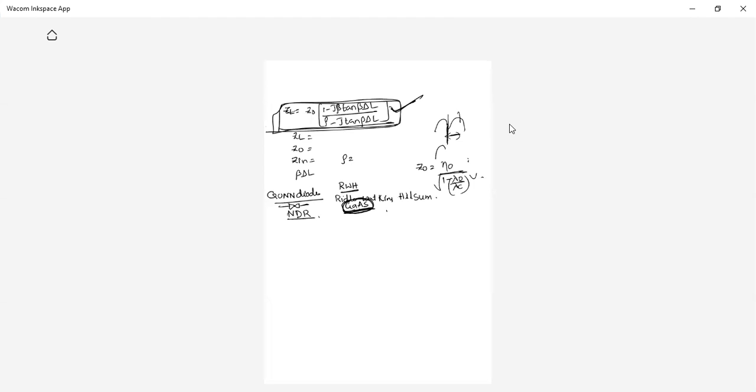What do you mean by negative differential resistance characteristics? Whenever negative resistance characteristics are observed, in this region we can operate that particular device as an oscillator. That means the Gunn diode can be used as an oscillator. That's what Ridley, Watkins and Hilsum observed.